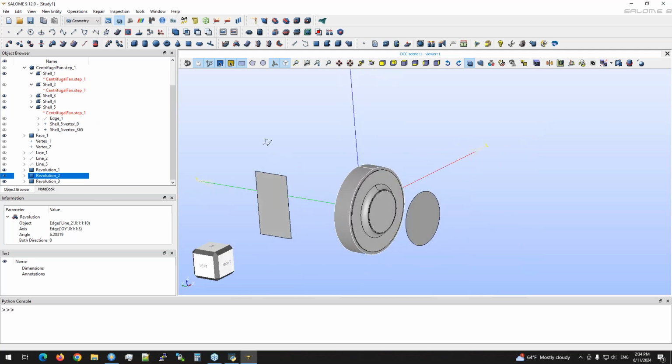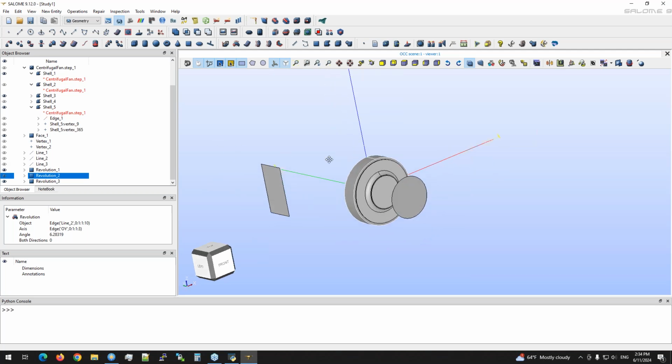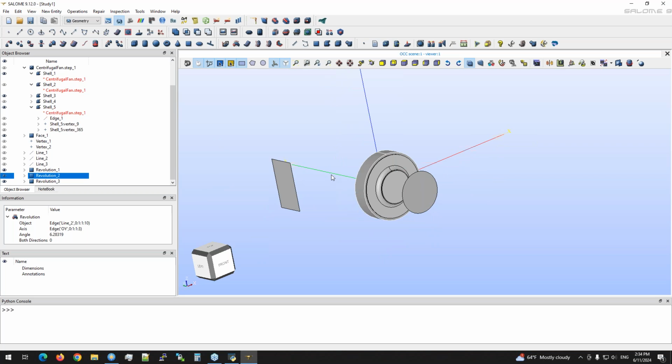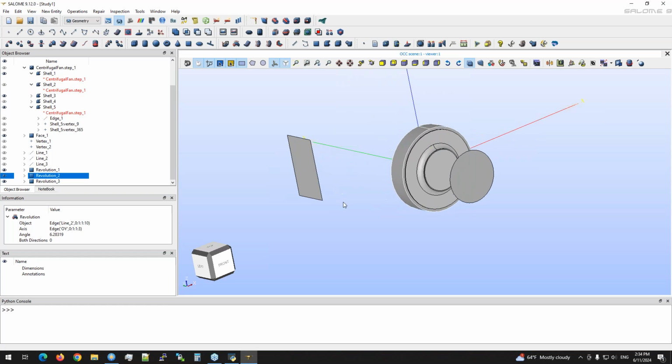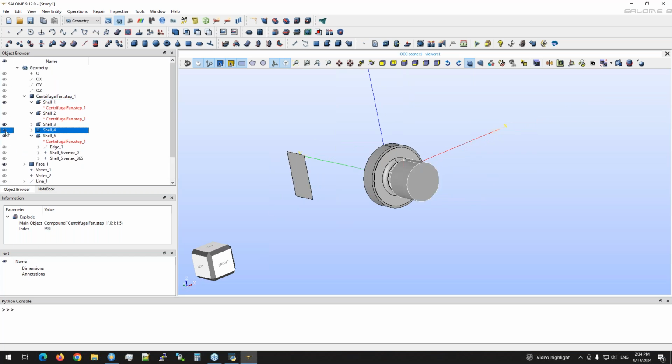What can I show you as an example? CFD typically likes extended outlets, because the boundary condition works best at the part where the flow is steady, homogeneous, and no big recirculations are happening. So sometimes it's nice or clever to define extensions of the volute. So just let me visualize the volute.